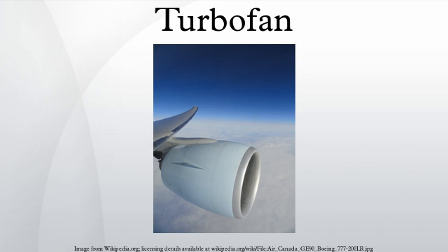At high flight speeds, high specific thrust engines can pick up net thrust through the ram rise in the intake, but this effect tends to diminish at supersonic speeds because of shock wave losses. Thrust growth on civil turbofans is usually obtained by increasing fan airflow, thus preventing the jet noise becoming too high. However, the larger fan airflow requires more power from the core. This can be achieved by raising the overall pressure ratio to induce more airflow into the core and by increasing turbine inlet temperature. Together, these parameters tend to increase core thermal efficiency and improve fuel efficiency.